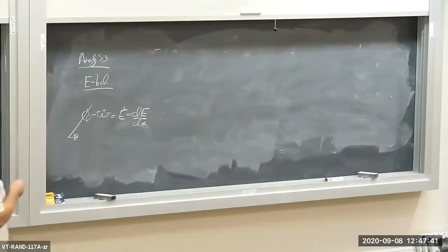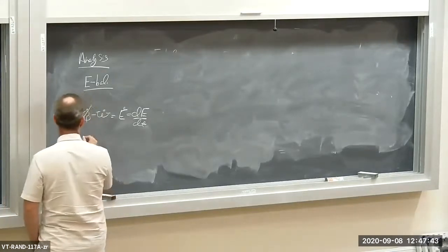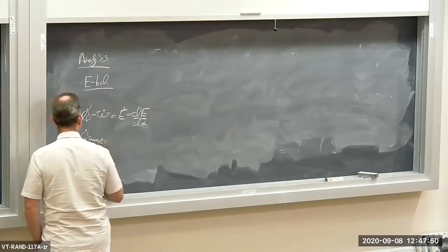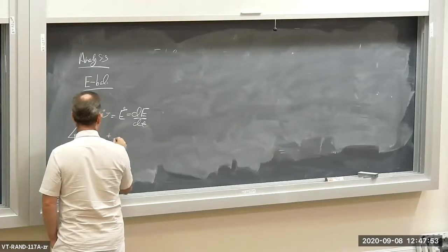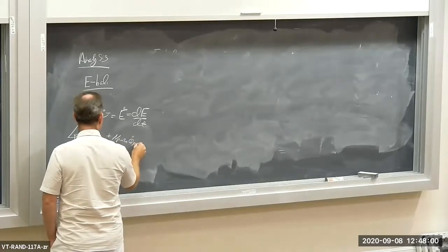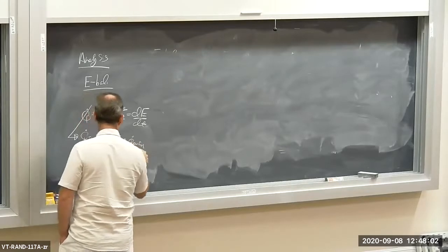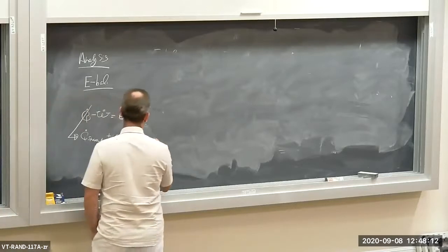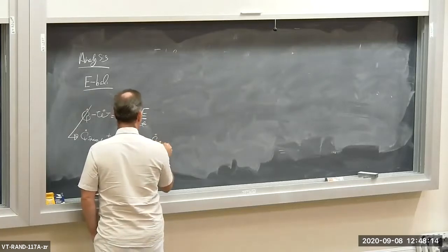So there are 3 different sources of heat transfer. There's the Q dot surroundings. We have the N persons times Q dot person. So that's the total heat transfer due to all N people into the room. And then I have minus Q dot AC.